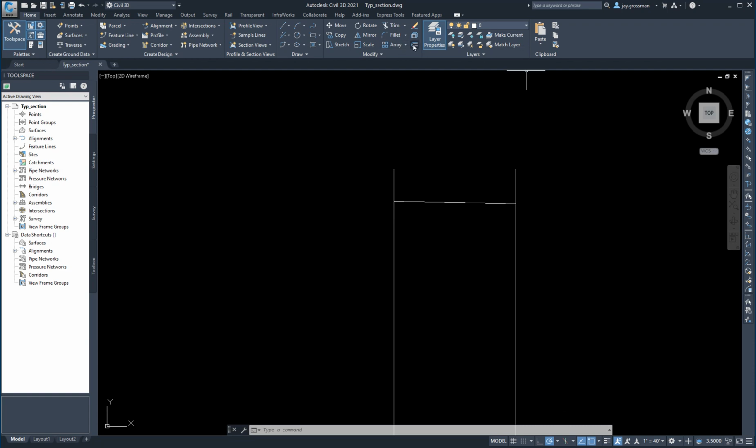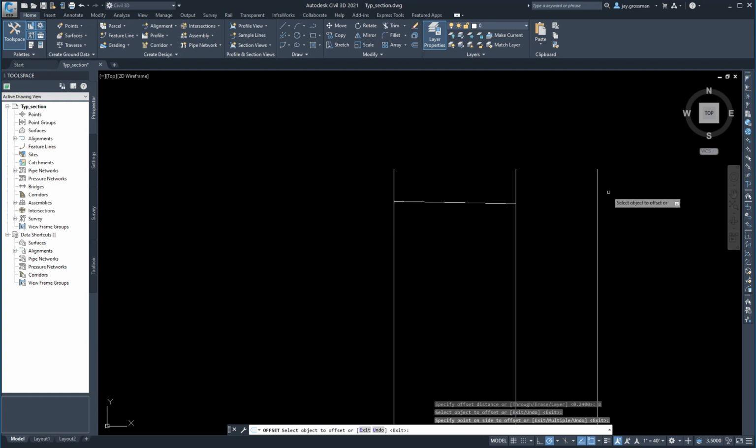So the next thing is, how wide is your shoulder? Let's say you've got an 8-foot shoulder. I think most of yours is probably bigger than that. I'm going to use 8. Right? So I'm coming over 8 feet. Well, what's the slope on my shoulder? Maybe it's 4%. That's a pretty common slope for shoulders. Paved shoulder would be 4%. So 8 feet times 0.04, it's a drop of 0.32.